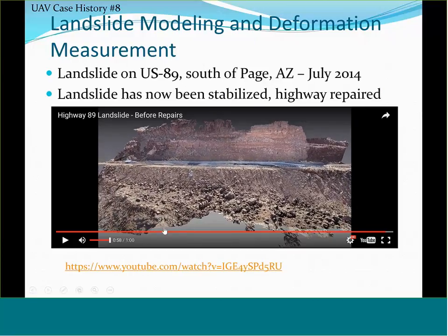But again, one thing that Dimitrios mentioned earlier that I'd like to point out, you can see zones of shadow across the road, and this was because we were flying very early in the morning before it got to 120 degrees air temperature. And once it got above about 100 degrees, our UAV started having malfunction problems. So you can see the impact, the shadows on the road. We were still able to create point cloud models, but the points are obviously discolored because of the shadows.